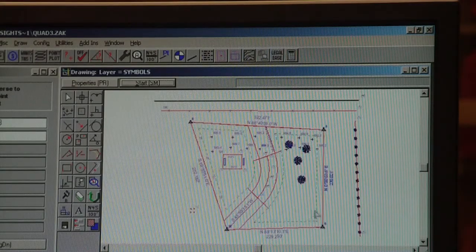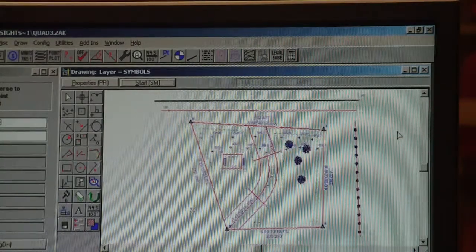So anything you shoot out in the open would be one of your grid points, because there was nothing or no reason for you to normally target out in the open grass. And we want to know what the elevations are out in the open. So if I had a lot of trees that already have elevations, I need to do the grid in the portion of my quad that has no reason to be targeted, so I have to create that reason, and that's a grid, 50 by 50. So I would try to get ground shots to produce a 3D coordinate.